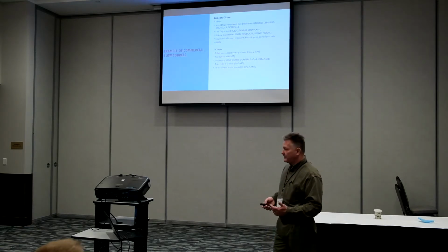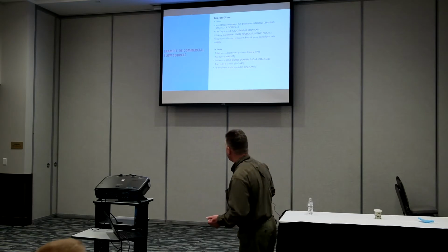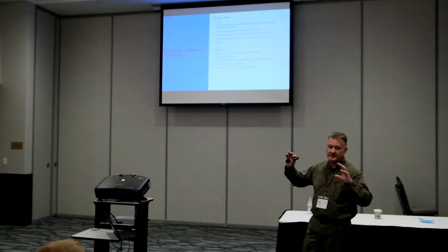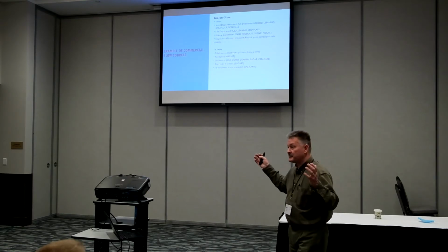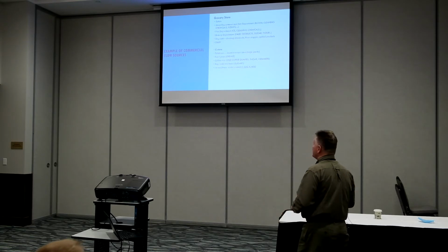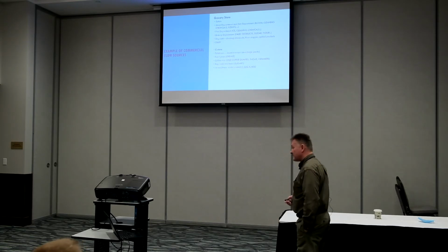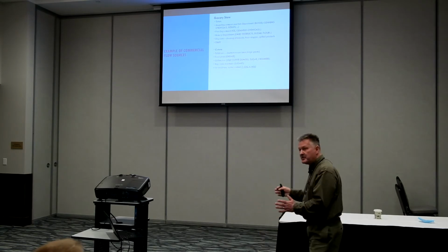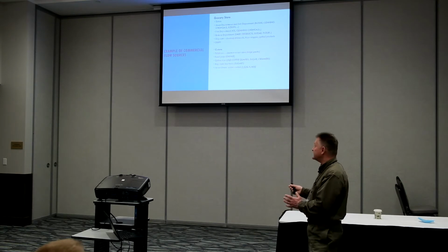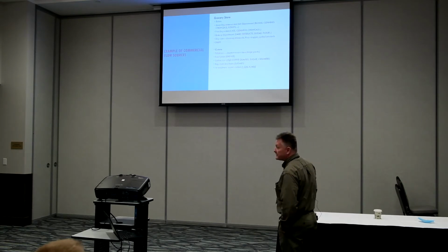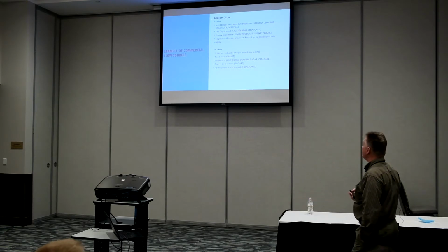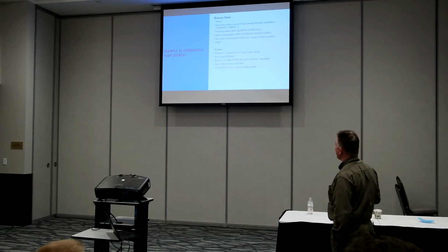So, examples of commercial flow sources. Let's say we're designing a grocery store. We can't just think, okay, based on square footage at a grocery store, we need a 3,000 gallon a day design. We need to look at all the sources. In a grocery store, there are multiple sources of input into that system, and each one of those inputs has different characteristics that can impact that system. For instance, obviously you're going to have toilets in there, primarily for employees. Occasionally some grocery store shoppers will use them, but we're going to have a meat department, and the rest of these are all gray water.